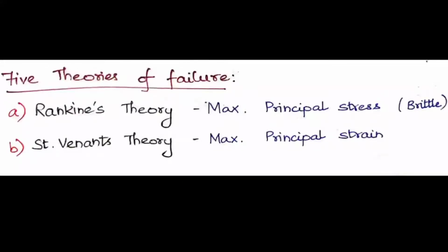Before going into this, why are we studying this? When an element is subjected to any load or any stress, how is it failing? Whether it is failing by brittle or by ductile failure has to be studied. Based on the behavior of that material only, the design has to be altered so that we make that structure safe.